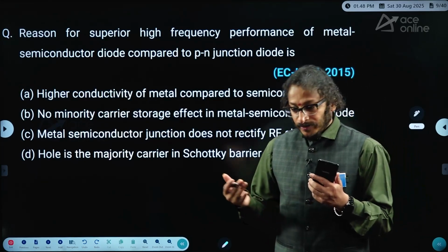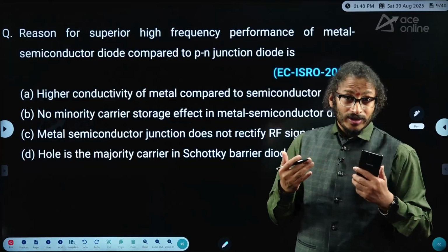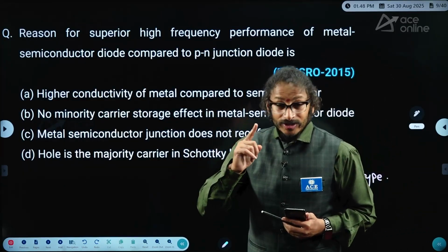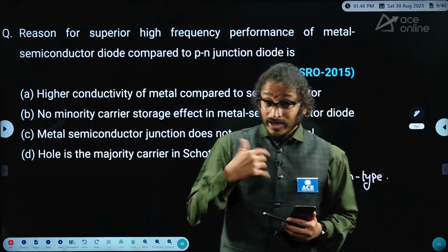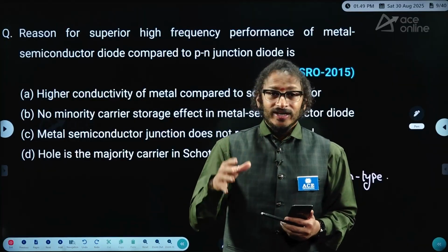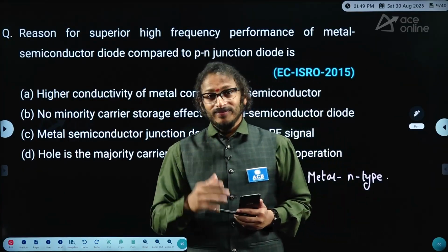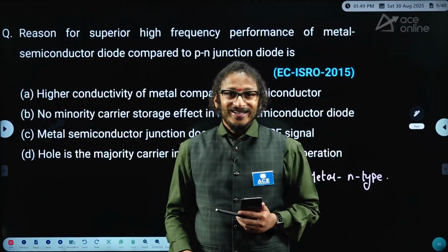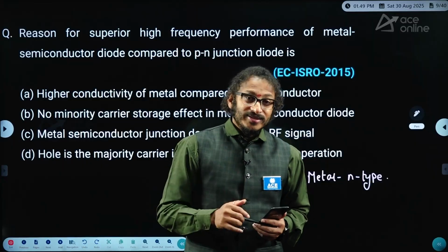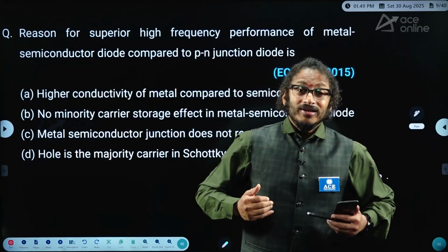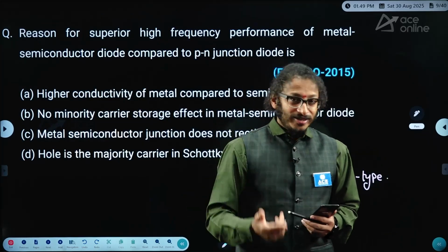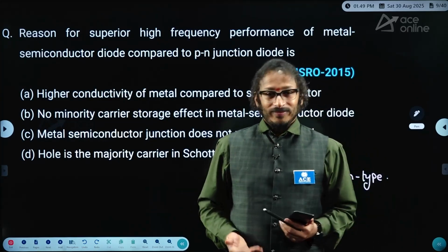As I already told you, for example, let me go for switching of a diode, or the transient behavior of a PN junction diode. Due to the capacitance behavior, if a diode is switching from forward bias to reverse bias, immediately it can't be shifted to the reverse bias. Due to the capacitance nature, it never accepts sudden changes in the voltage. It takes some time, that is the so-called reverse recovery time. In the reverse recovery time, what is included? One is the transition time, and the other is the charge storage removal time.